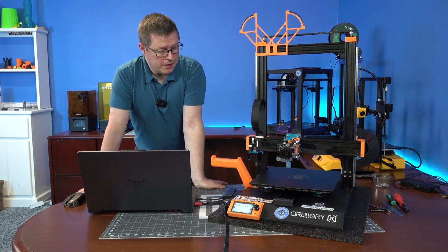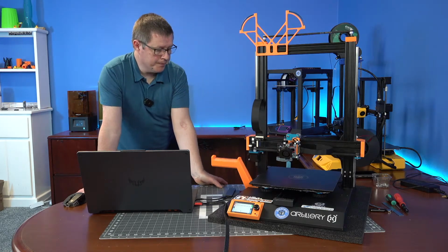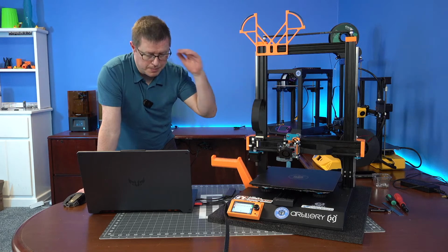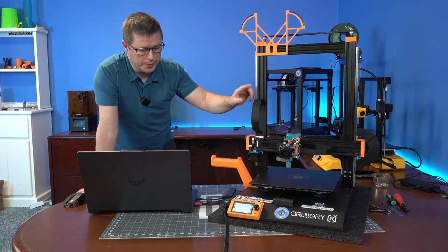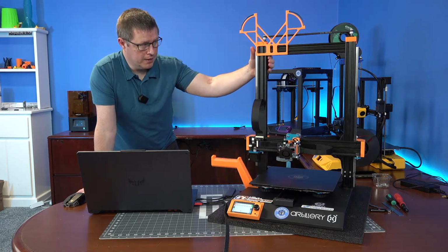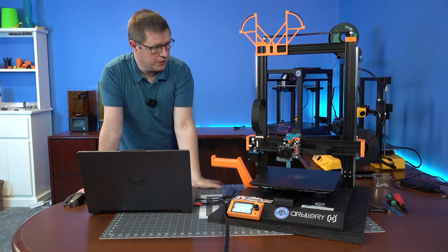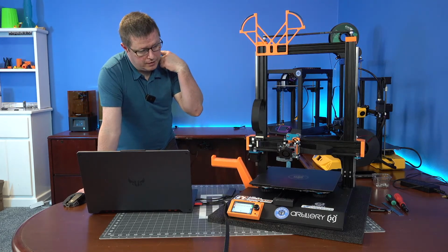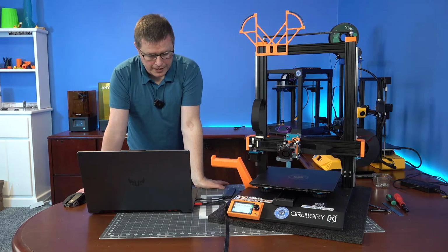Obviously, I'm not printing any thinner layers like 0.15, but it's a smoother, better setup than the original plastic roller wheels, and part of that is because the frame on this isn't quite right. The uprights are tapered at the top, so it had issues with binding. So this was my fix for that, and I have more stuff I'm going to do in the future on it. So hopefully that explains it.